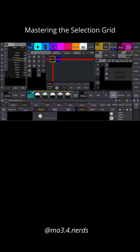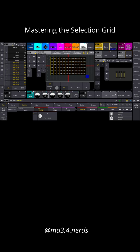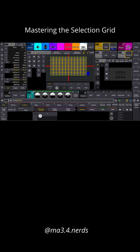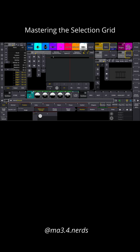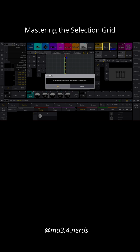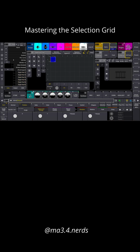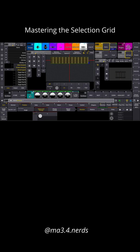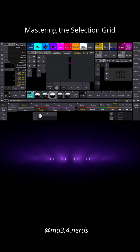If I select fixture 500, hit down, then hit camera to grid, compress it, hit down again, you'll see that in this case, some extra subfixtures appeared in my selection grid, but this is okay. I'll simply type -*.1 through 2 in my command line, which will release to the .1 and .2 instances, and then now that just my .3s are selected, I'll hit down again. By default, these fixture types typically have their pixels oriented horizontally, but in this case they're mounted vertically. So I'll clear out, then I'll select one .3 instance, hit down, rotate it 90, type grid store, OK, clear out, select fixture 500, move down, camera to grid, compress it, hit down again, -*.1 through 2, then hit down again, and now the fixtures are oriented vertically.